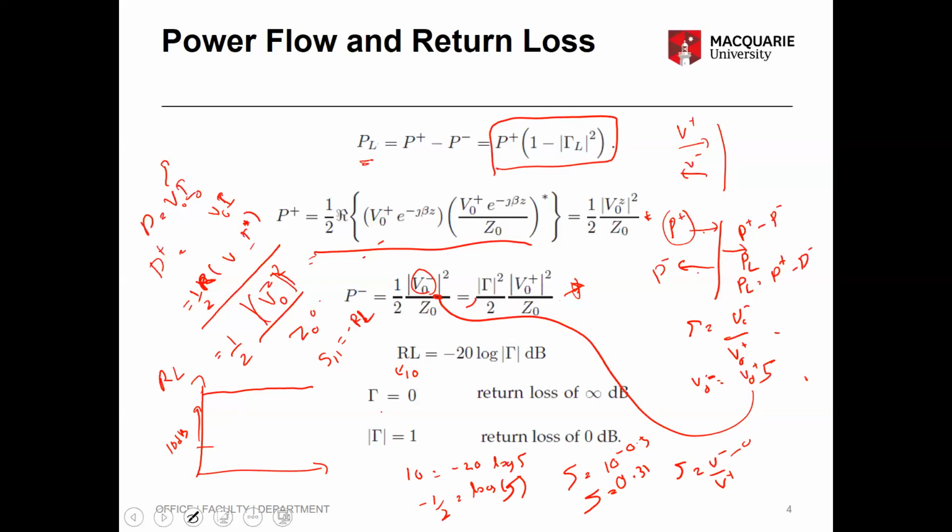So only about 30% of the voltage is reflected back when you have an input of 1. Out of that, 0.3 of the voltage is returned back. We think that's sufficient for most systems, in terms of voltage. So that's what it means. As long as the return loss is a larger value, that's good because you have less reflections. Now what happens if tau is 1?